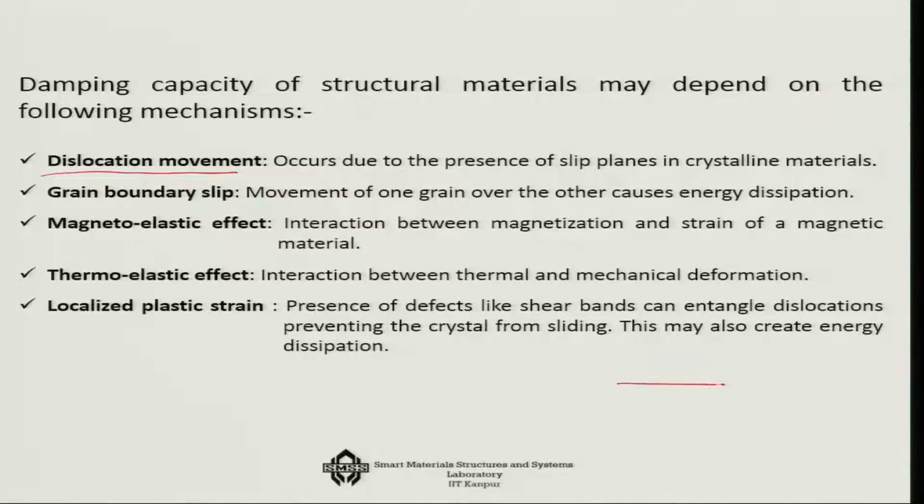If you consider a small structural material and look at it using a microscope with something like 100x magnification, and it is a metal, for example, what you will see is that there are various grains, and the grains are crystal structures which have one single direction of orientation, maybe one in this way, another in this way. So, these are directions of crystal orientation. Now, in the first case, the dislocation movement, if there is any failure inside this grain, then during the movement it goes to the boundary. That is our dislocation movement.